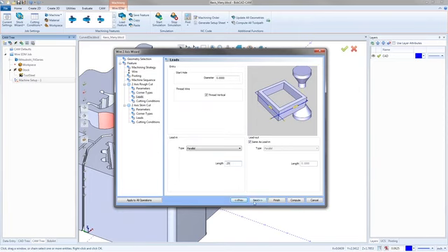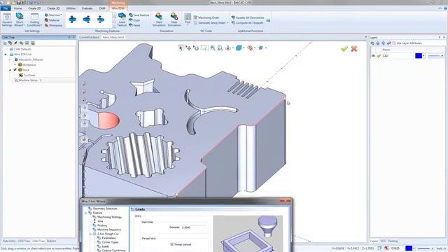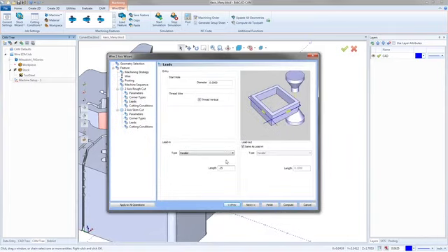You can use your leads to take care of some of the cutting for you, especially these parallel leads. All you have to do is overextend them and let the wire come in a little earlier and exit a little later, and you've just cut the entire part, even though all we've selected was this chain here and not that radius in the back. So I think a 1/4 inch should be long enough. We'll find out.